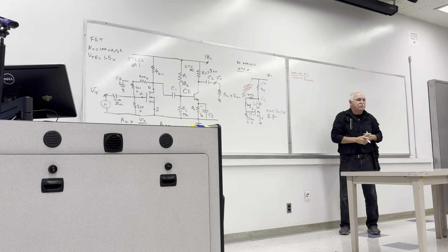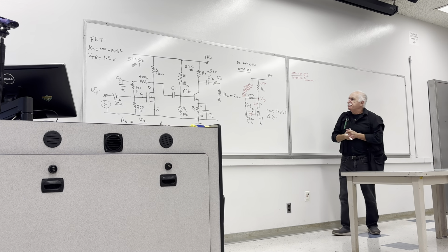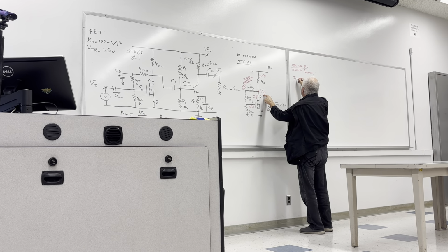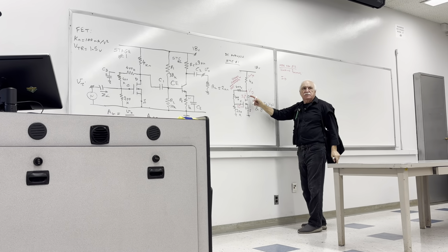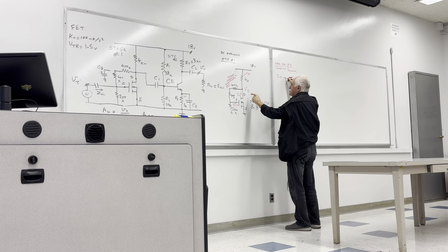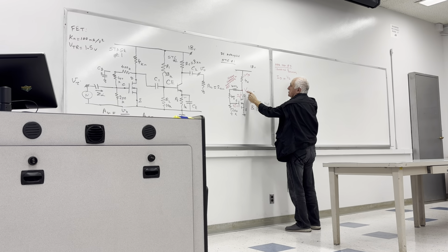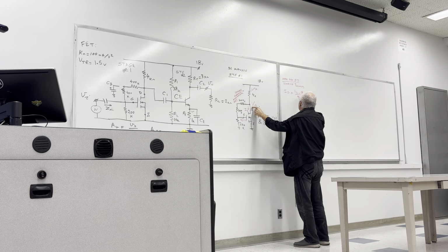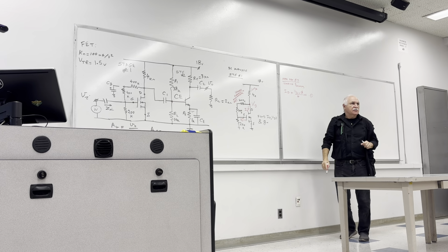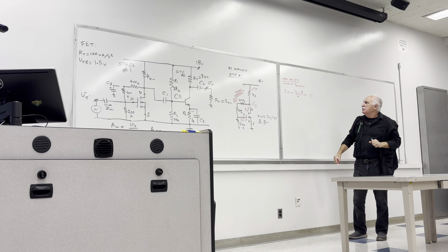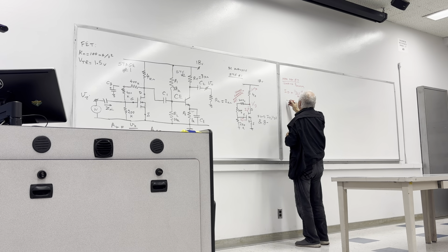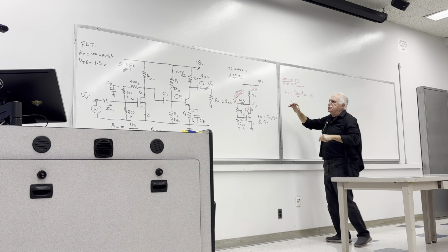We're ignoring that current. So let's see what will come out of it. Node equation. You will have ID, current going this way to the drain, plus V of the D, voltage of the D, minus 18 divided by 4K equal to 0. Equation number 1, okay? So let us organize that. Okay, we can do it one step later.